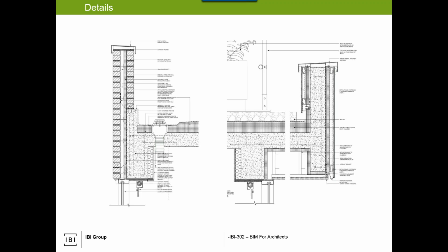But the beauty of that is, if the slab thickens or moves or the wall moves, that backbone will show over the detail, and then you know you have to adjust your detail overlay accordingly. So that's the benefit of using the BIM model, even for the basis of the details, specifically for project-specific details where it's dependent on the geometry.